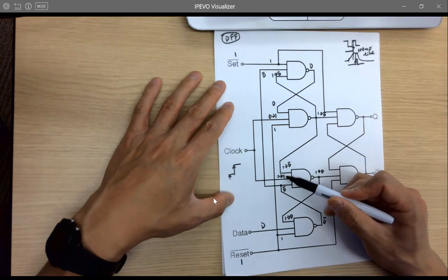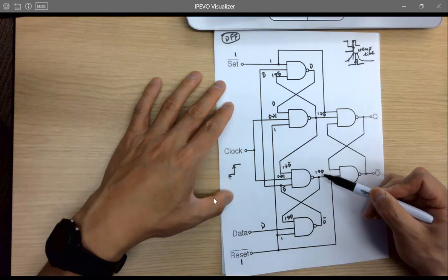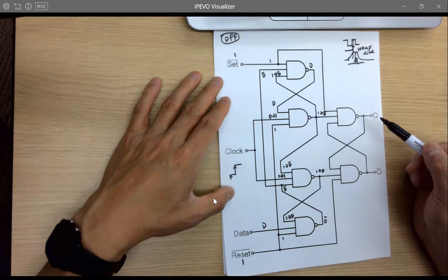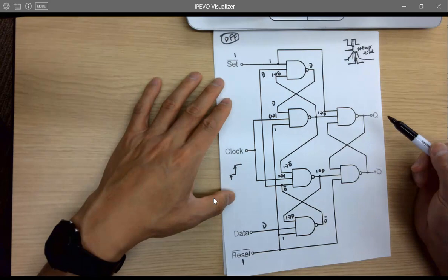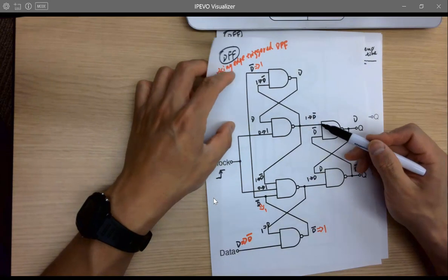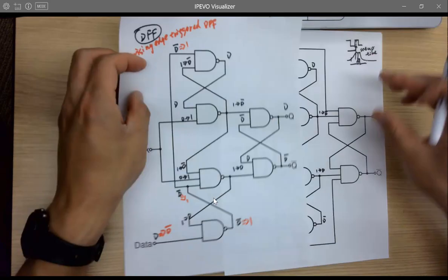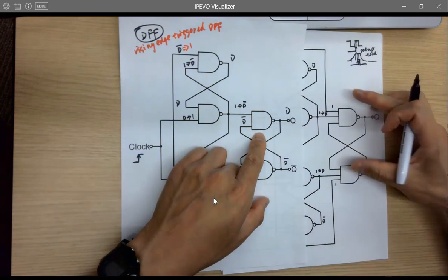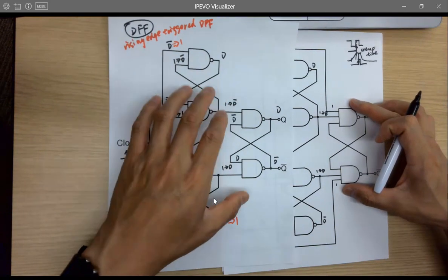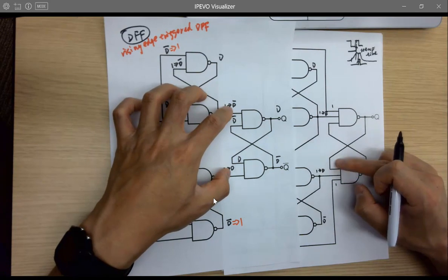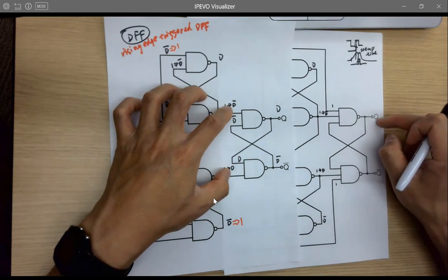Same here, D naught, 1, D naught, D, stable. Do we need to update any other places? So we're good, right? So it's very similar to this one. It's just adding one more signal line on the top. But if you compare these two gates, the signal on the top is always 1 because we're not setting or resetting it, so it's not changing anything. As long as we have the same signal over here, it should do the same job. So if you have D bar and D, Q should be D, right? Okay.